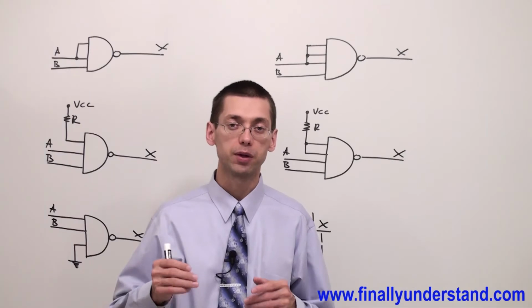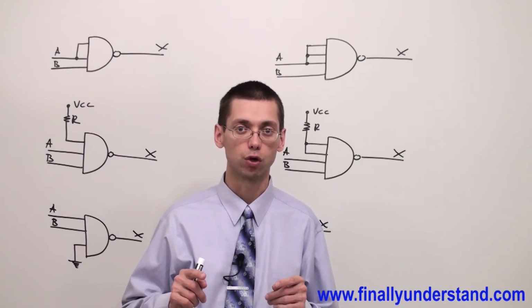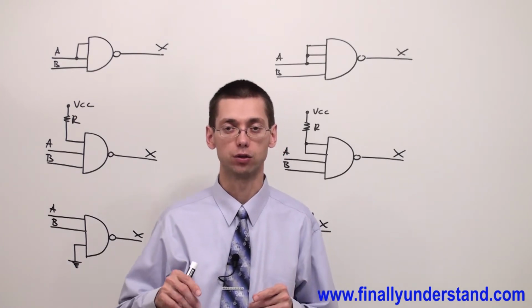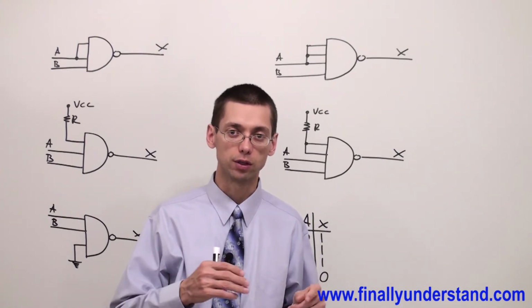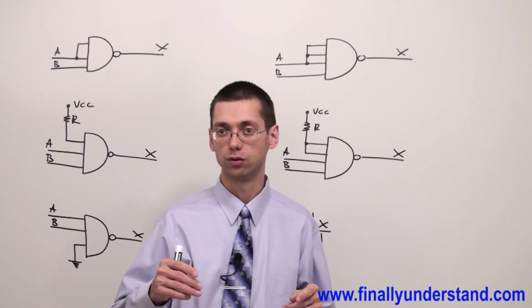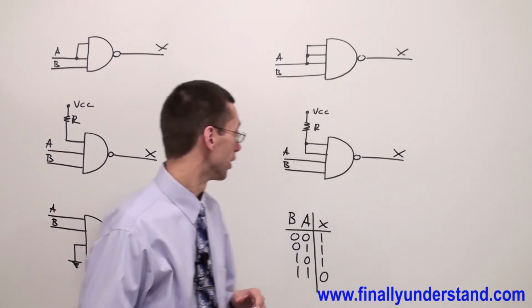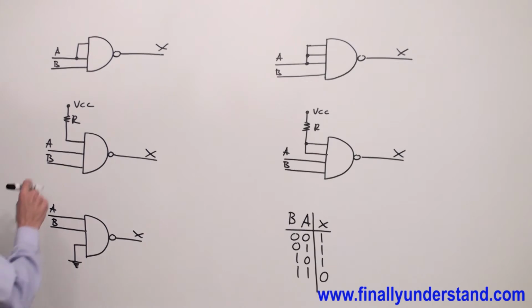This time we are going to discuss NAND gates. Always keep in mind that you cannot leave any input connected nowhere. The input is supposed to be connected to VCC, to ground, or to the output of the other gate, or let's say to a pull-down resistor or pull-up resistor. Okay, so let's verify which one of these circuits is correct and which one is not correct.